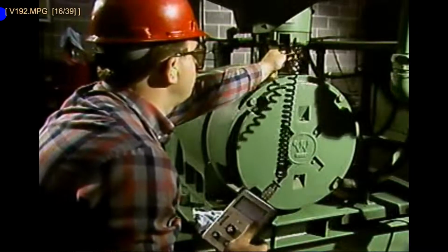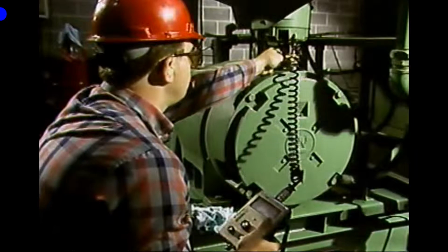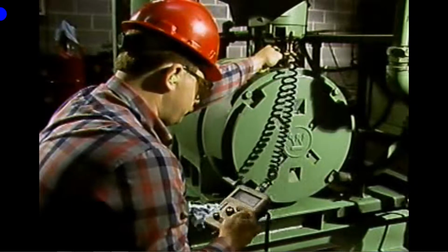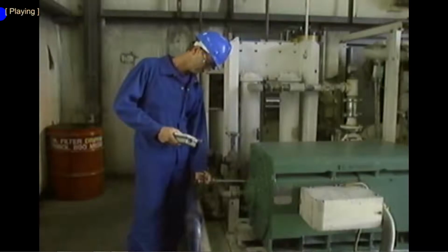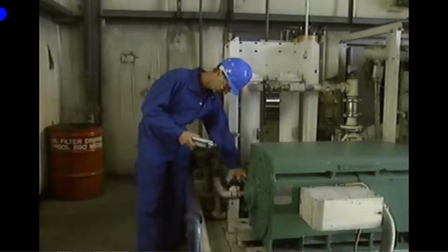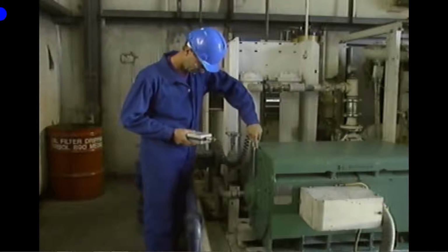Transducers can be placed on a machine in a number of ways. The method used in a particular application may depend on the type of machine that is being checked. If a machine that is being checked for vibration has more than one set of bearings, each bearing should be checked if possible. Also, if possible, each bearing should be checked from 3 different directions.